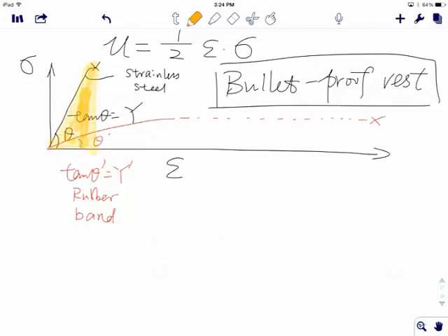So it's the area of stainless steel, SS, that just equals, since it's a triangle, 1/2 times whatever this stress over here is, times whatever this strain here is, right? This is how you calculate the area. Agree? Triangle, right? Okay.